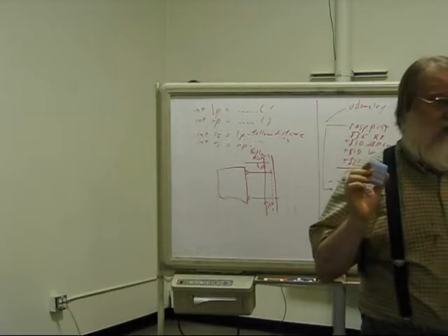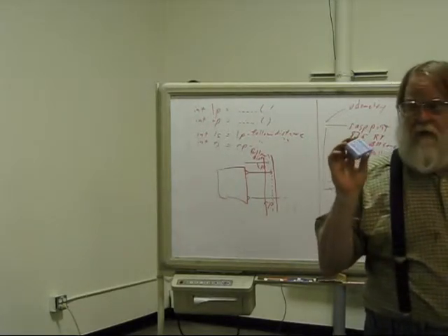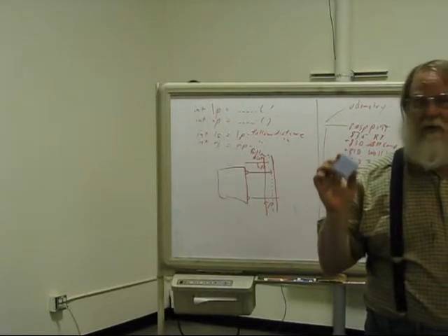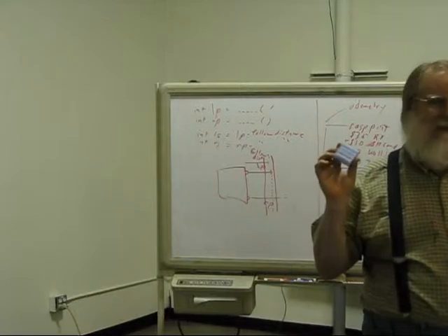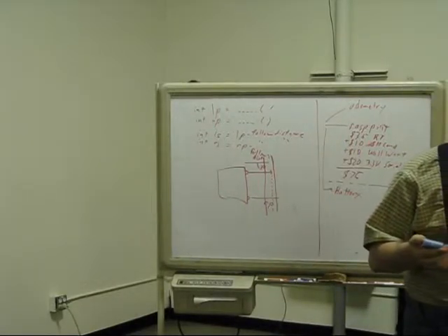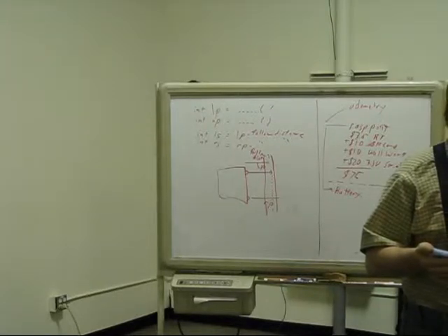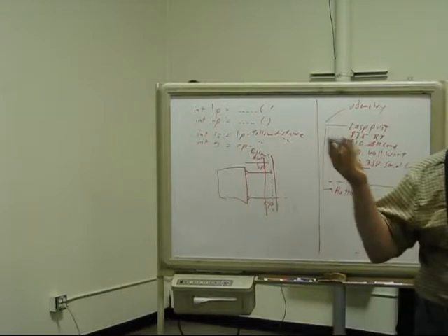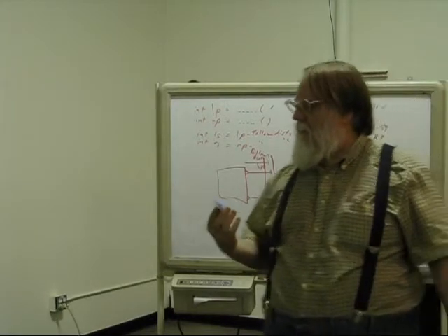You need the charger though. The charger's about $30 for a really good smart charger. Let me warn you folks, don't buy a cheap charger. You're wasting your money. The only thing you need a cheap charger for, if you have a smart charger, is if these ever drop low enough, the smart charger won't see it. You have to give them 5 minutes in a dumb charger to get the voltage up enough that the smart charger will take over.